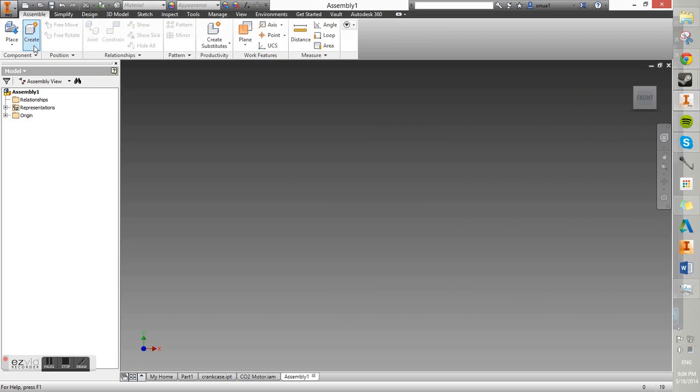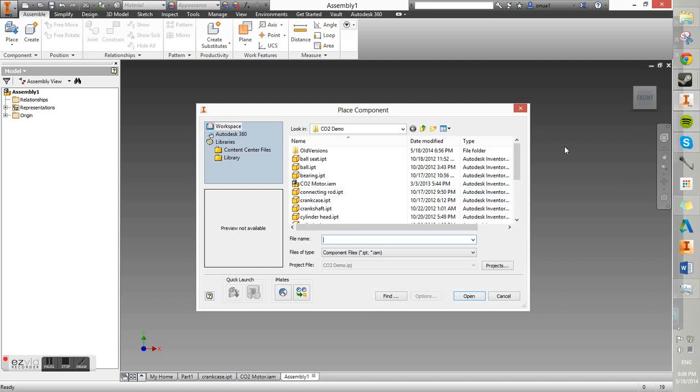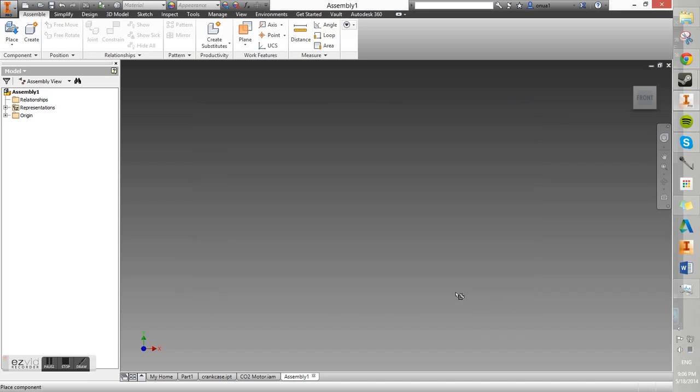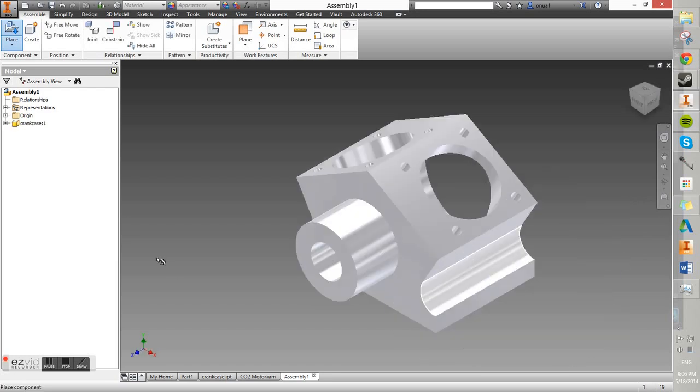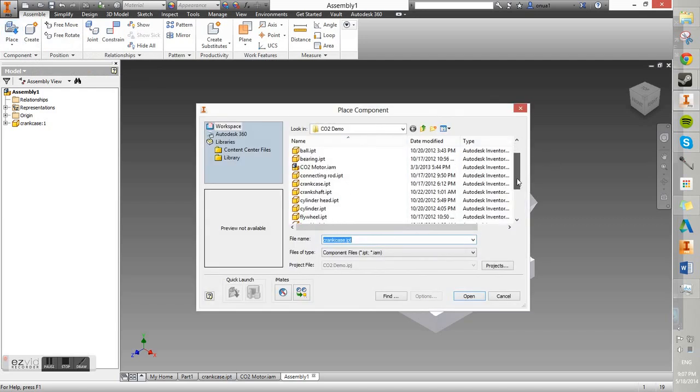This is what an assembly looks like. There's nothing in here, since you have to place pre-created parts from part files into an assembly and join them together. So these pull directly from your workspace, which is associated with your project file, which is why you need to make a project. So your first part should be your base part. You can make multiple iterations, but you can just hit Escape or right-click OK to keep whatever parts you want there at the moment.